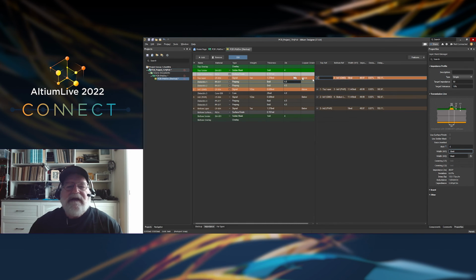So let's see, when I use a 1 mil thick solder mask, I'm going to use a dielectric constant of, they're closer to 3.2 typically. So I'm going to use 3.2 as the dielectric constant. And now I'm going to turn on that solder mask. And when I turn on the solder mask, I'm going to assume that I have the same thickness covering in the general regions as on the material.